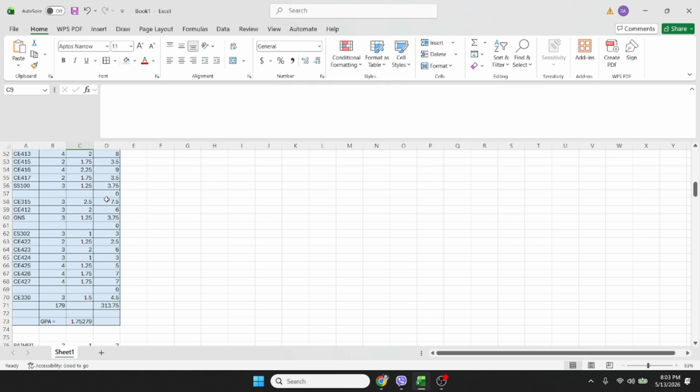And we're interested now in shear. And the phi for shear is 0.75. It is the same as the earlier strength reduction factor for moment, axial force, or combined moment and axial force.